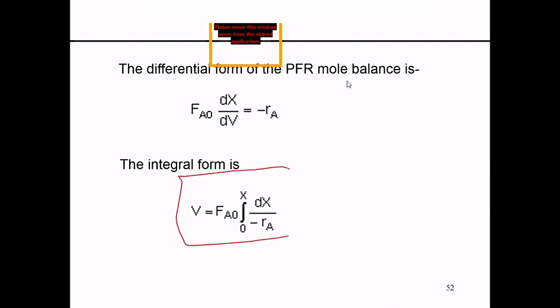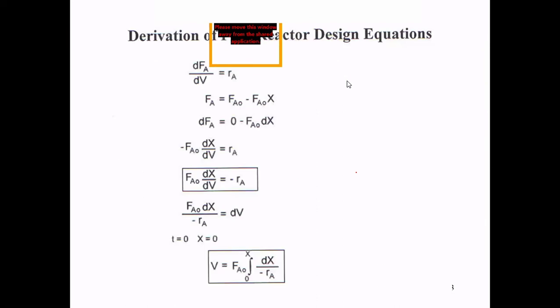At the end, we got this, similar with the equation for the plug flow reactor design equation. So when you want to design the reactor, normally you will use this equation, because from here you can get the volume needed and also the space time for the reaction.